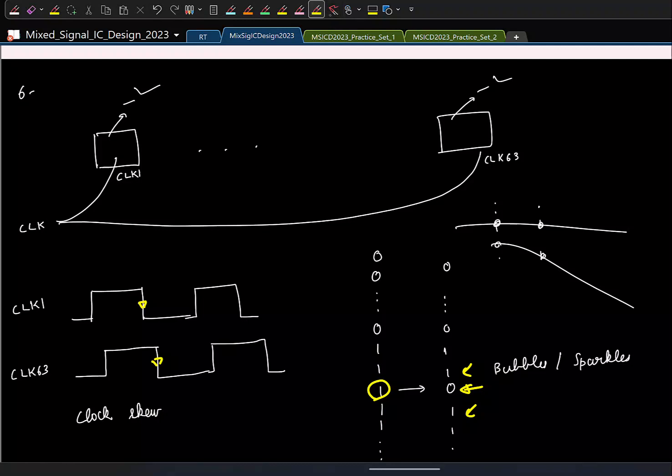Okay. So what is commonly done is to have a global sample and hold or a global track and hold. This will be a simple switch and a capacitor. And of course the capacitor output cannot be given directly, so you have to buffer it. This could be a simple common source amplifier, common drain, source follower. Here you don't have to do that switch capacitor amplifier and stuff, because remember that the maximum resolution in a flash is say 6 bits.